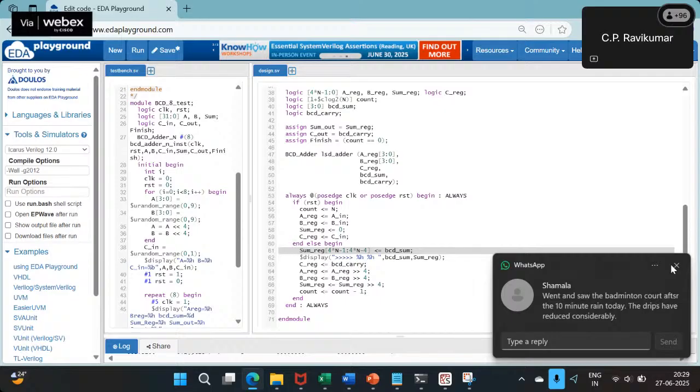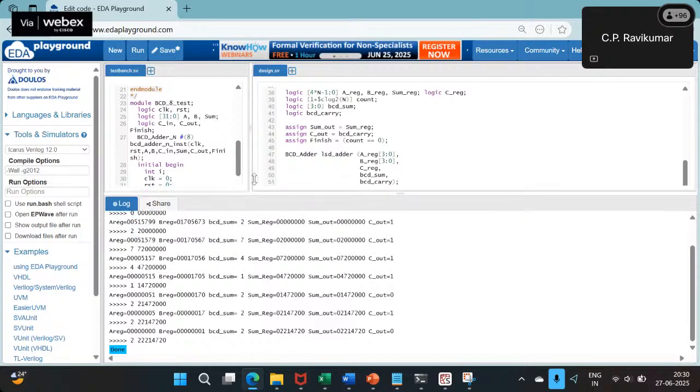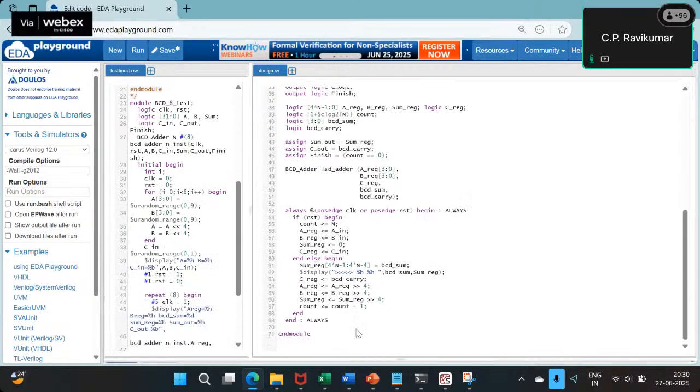non-blocking assignment. Okay, so non-blocking assignment is the issue because we are not waiting now, we are immediately going ahead. That is the problem. If I change this to this, it will work. Let us say initially it had 0, right?